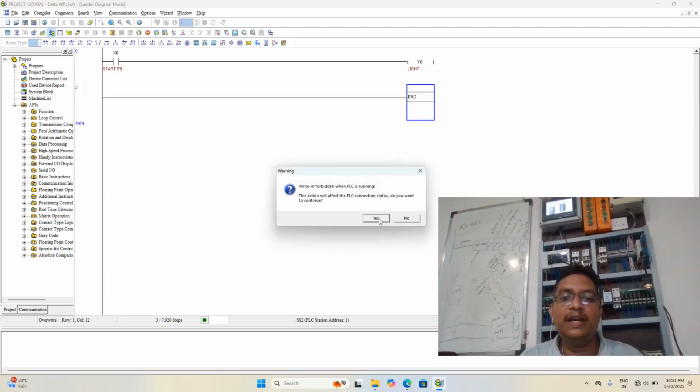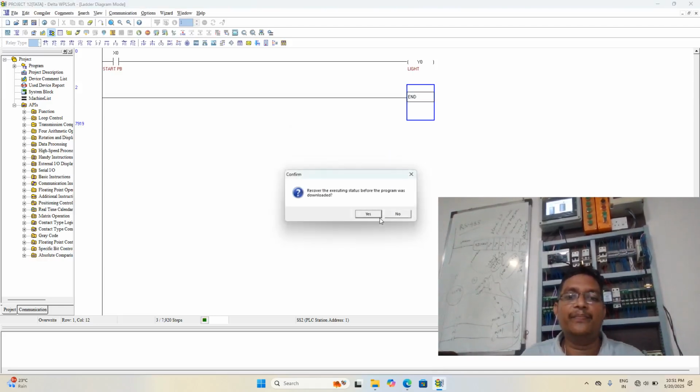and selecting yes. Okay, now you have to be careful. When you download the PLC program, the existing PLC program will be deleted or erased permanently. So be careful before downloading: you have to save a backup of the program before downloading it.